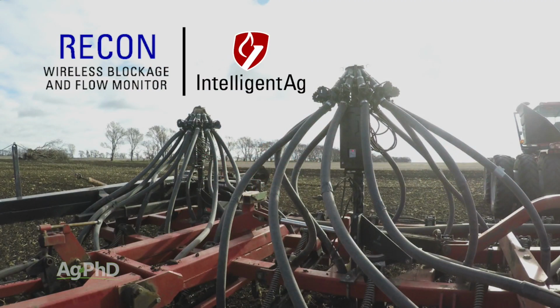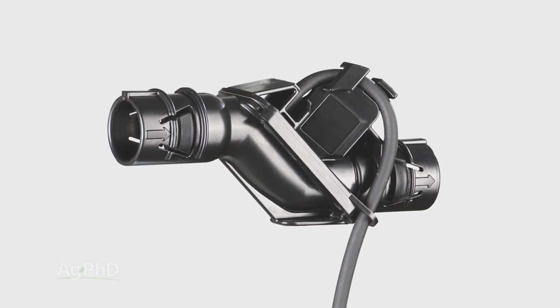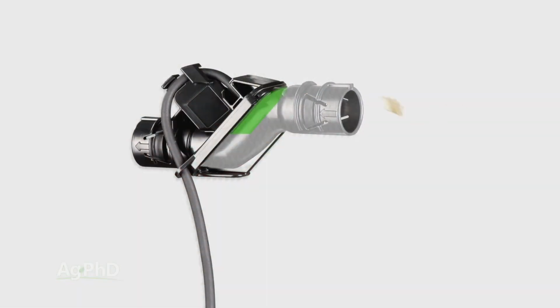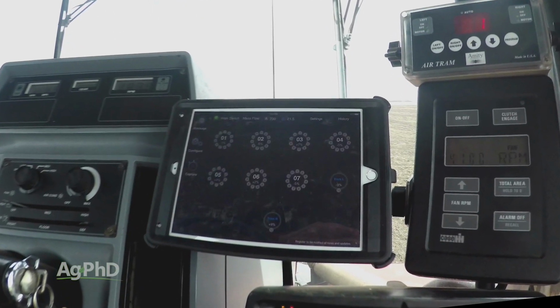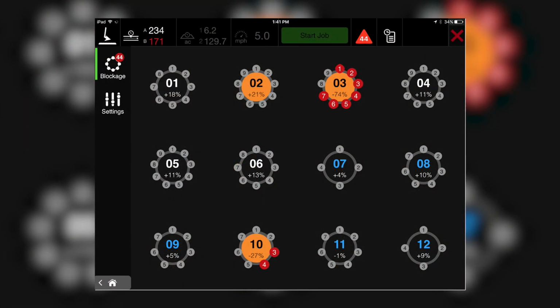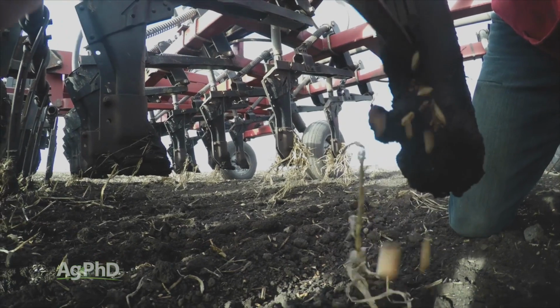With Recon, it actually uses acoustic sensors, so rather than seeing the seed pass through, it uses a mechanical sensor that works like a stethoscope. As seed leaves the manifold, it passes through the sensor and reflects off a stainless steel membrane, which creates a sound. That sound is converted to a digital signal and sent wirelessly to an iPad in your tractor cab. It's simple to install, reliable, and gives you peace of mind knowing any issues with the blockage or flowability issues can be identified and solved quickly in the field.